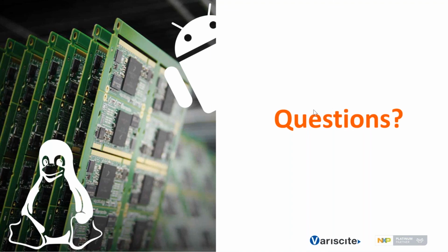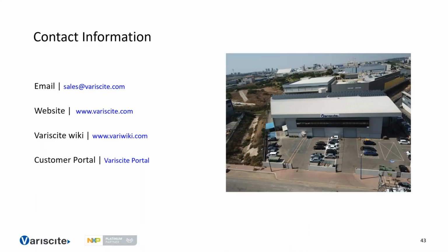Basically, what you need to do is add the right packages. First of all, you need to identify the packages. Just remember that we rely on the NXP based BSP. On top of it, we add our customization, but generally speaking, we provide the Yocto standard BSP based on Poky. There are some basic layers added, let's say meta-oe and meta-embedded or something like this, but you may require additional packages.